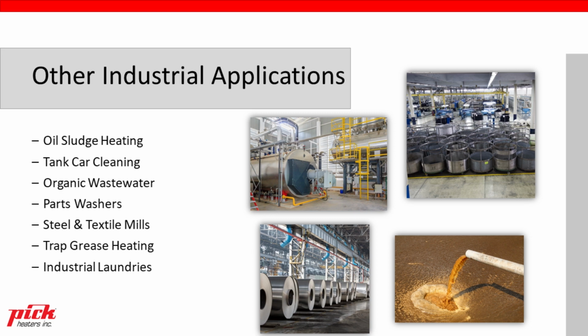Organic wastewater is done in a lot of industrial applications. Then parts washers. For instance, in the automotive industry, where you're making gears and parts for engines and transmissions, they're using a lot of cutting fluid. Well, I guess that gets into wastewater heating, but with the parts washers, they like to wash off those parts very quickly after they're machined. So using a steam injection heater is a great application.